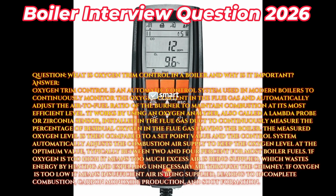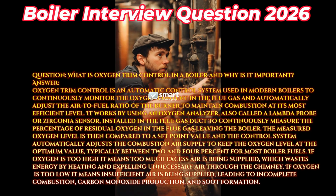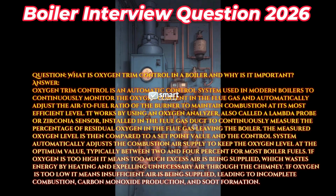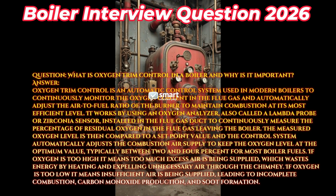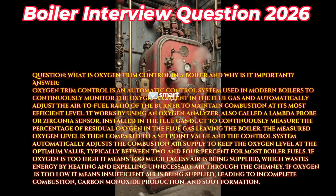It works by using an oxygen analyzer, also called a lambda probe or zirconia sensor, installed in the flue gas duct to continuously measure the percentage of residual oxygen in the flue gas leaving the boiler. The measured oxygen level is then compared to a set point value and the control system automatically adjusts the combustion air supply to keep the oxygen level at the optimum value, typically between 2 and 4% for most boiler fuels.